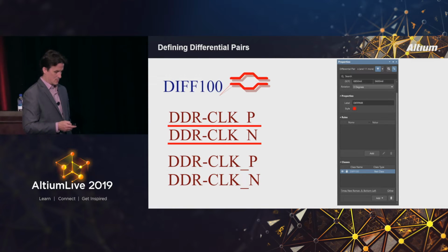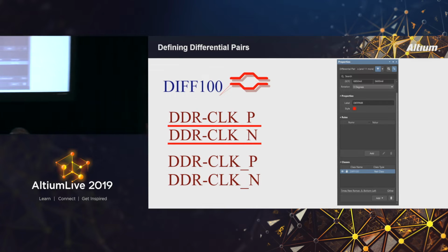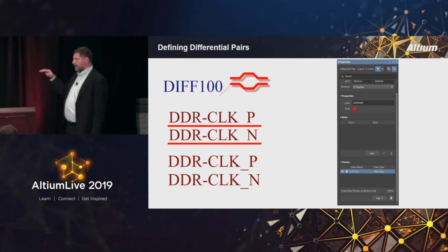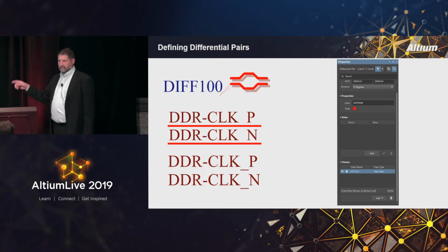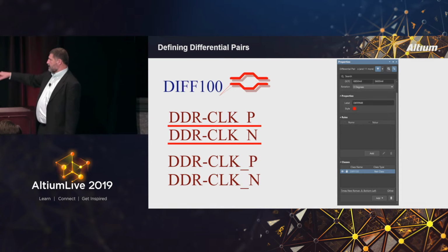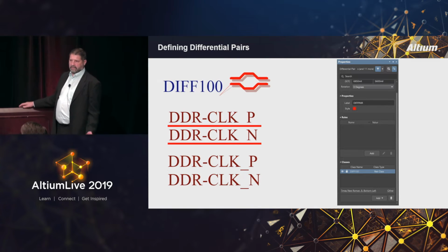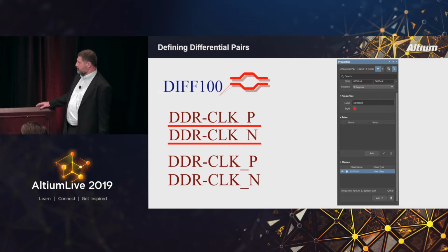And if you've created your stackup, you can import the stackup into the schematics now in version 19 and forward. And if you've also put your differential pairs into the stackup, now you can call those out here. It greatly simplifies the rule writing, and it carries that forward.